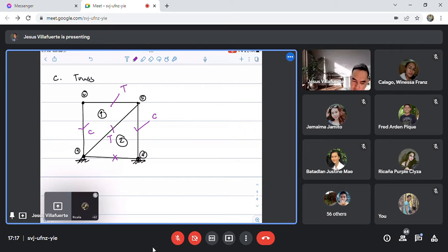the compression load and the tensile load. So there are no other loads. There are no bending loads. There are no torsional loads. That is just the two requirements when you analyze a truss. Number one, all the joints must be pin connected, meaning to say dapat walay moments, and then all the forces in the joints are only axial compression or axial tension.